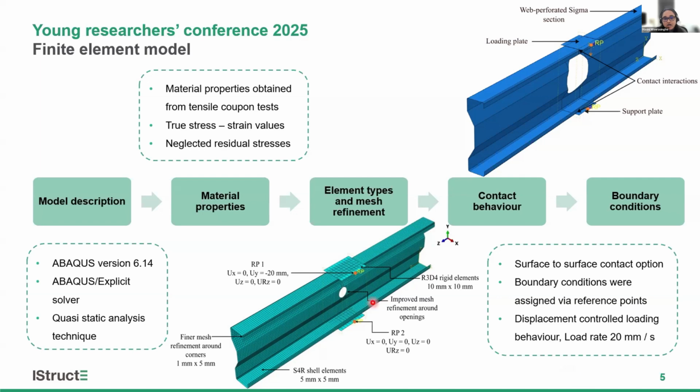And you can see how the loading conditions and the boundary conditions have been applied via the reference points of the loading and support plates. And the displacement control loading behavior was simulated considering a load rate of 20 millimeters per second.